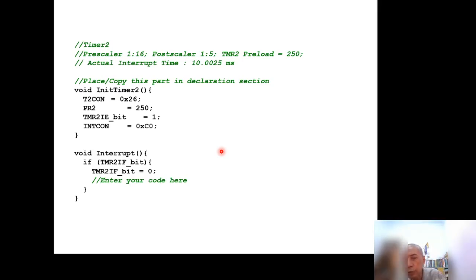According to these features of prescaler, postscaler, and frequency, you can select the internal or external clock, except for Timer2. In Timer2, you cannot select the internal or external clock, only the internal clock, which is always divided by 4. Just remember that.